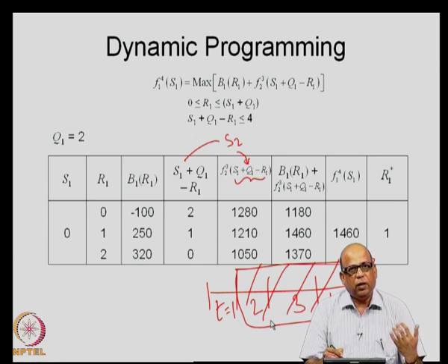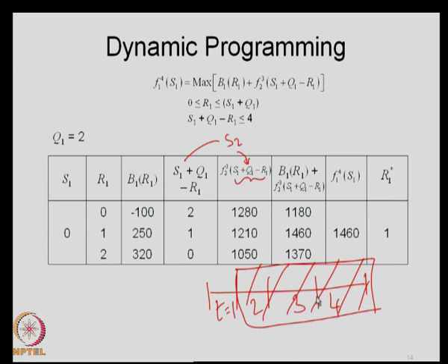Go to the time period 3 calculations, which is the stage 2 calculations, look corresponding to that particular storage, look up what is the optimal solution, and apply that optimal solution for this time period. Come to the beginning of the next time period, go to stage 1 calculation, which corresponds to t equal to 4, apply that release, and thus you get the releases during time periods 1, 2, 3 and 4. So, this is how we trace back the solution after we solve the last time period.